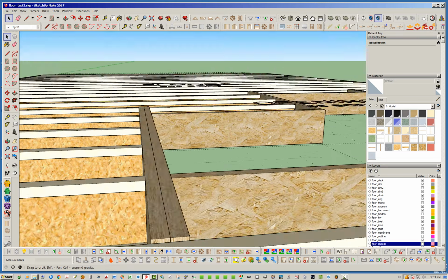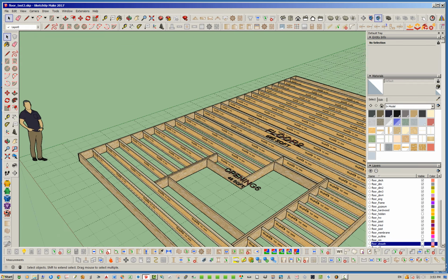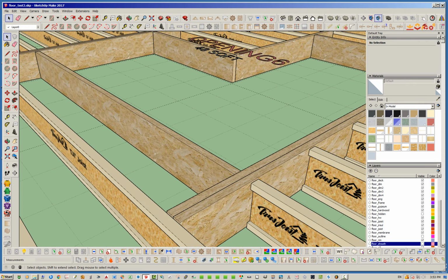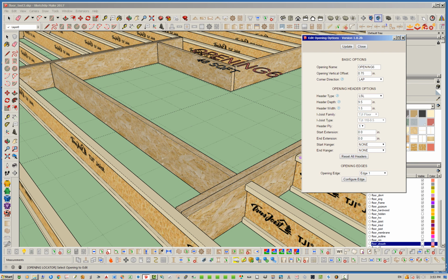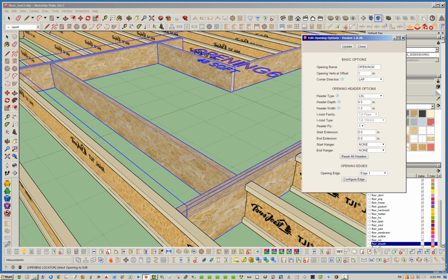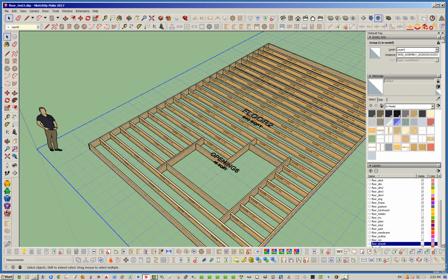All right. So it looks like it's a little proud there, and I think that's because we set our offset incorrectly. So let me check that. What I'm going to do is edit this, 0.75. For whatever reason it's up by 0.25 inches. I'm going to vertically offset that 1 inch. And there we go. Anyways, that's basically it. That's all there is to that tool. It's fairly simple to use, and it saves you having to put those numbers in.